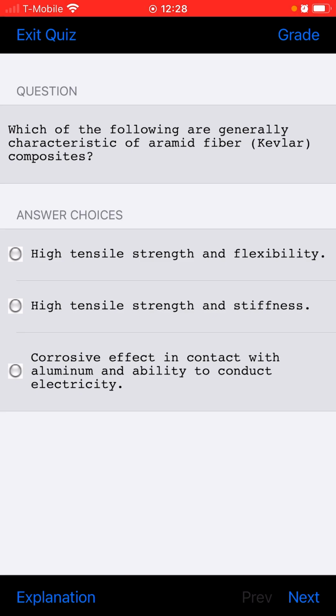Let's read that question again. That's a big question, and the ones that are big, I'm going to read them at least twice. If a streamlined cover plate is to be hand formed using a form block, a piece of dead soft aluminum should first be placed over the hollow portion of the mold and securely fastened in place.